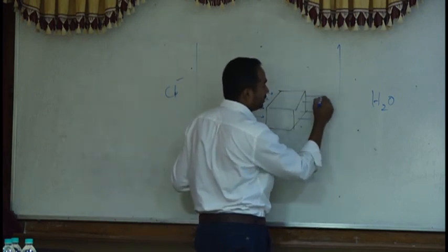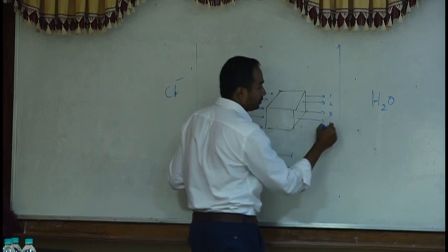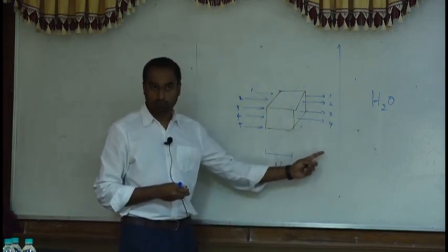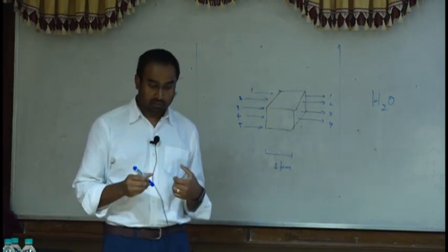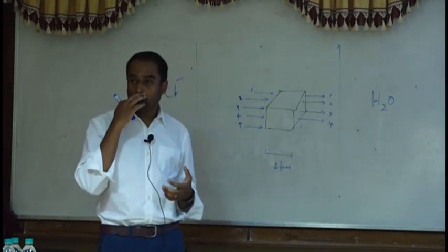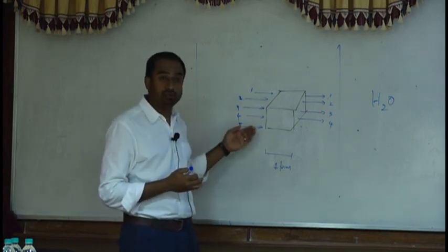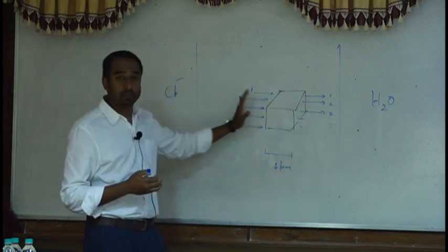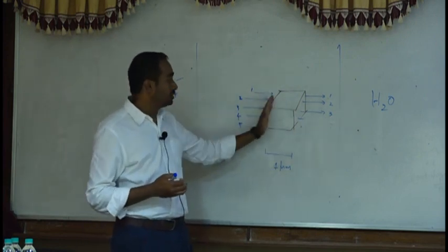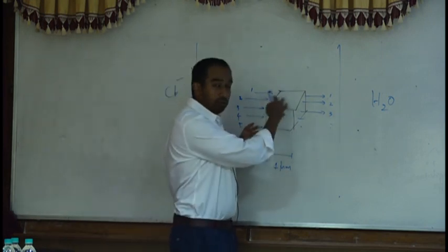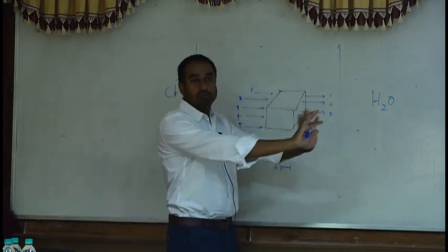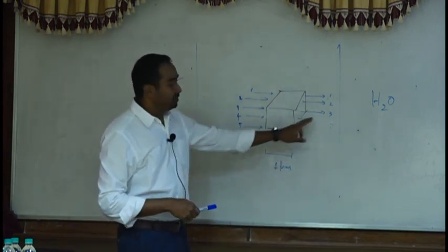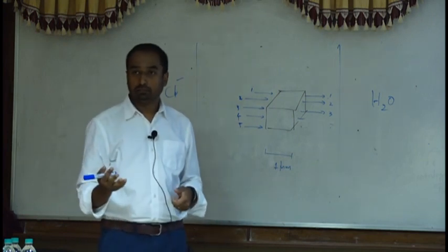Depending on what's in the concrete, there may only be 4 of them that can go out. Okay? If you're using PFA or any other substitute that has more aluminate phase in it, there may only be 3 of them going out. It's not the exact chlorides that come in that go out. So 5 of them come in, and of the chlorides that were available in the system, 3 of them will have to move out to make space for more. Okay. So that difference is what we refer to as binding.